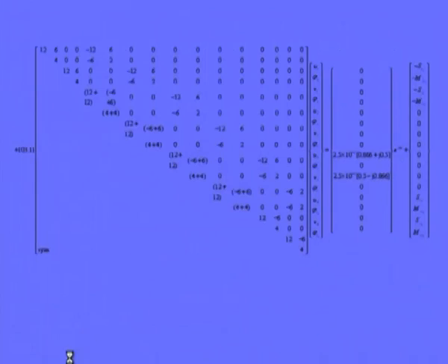Next is the stiffness matrix. This stiffness matrix is also of all the three elements, and this is the total external force vector, and these are the internal forces. You can see that the internal forces at the common nodes will become 0.